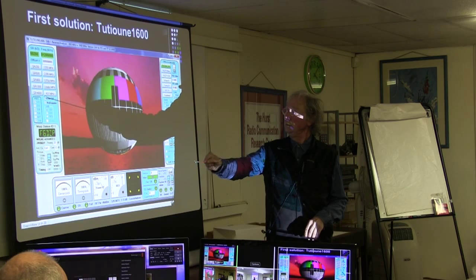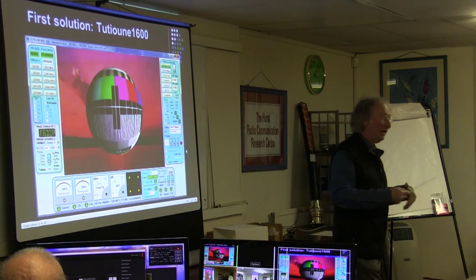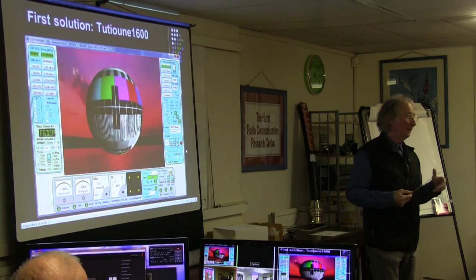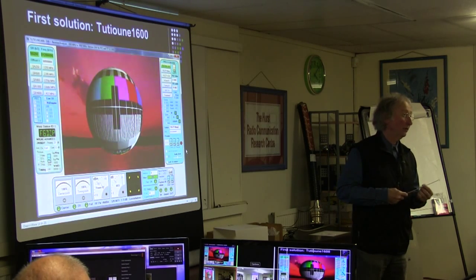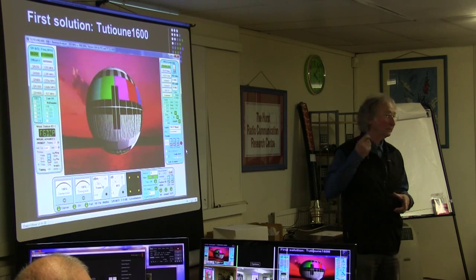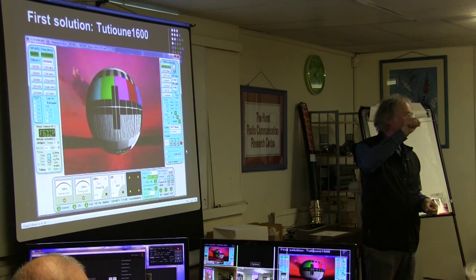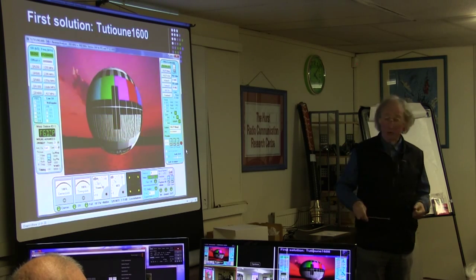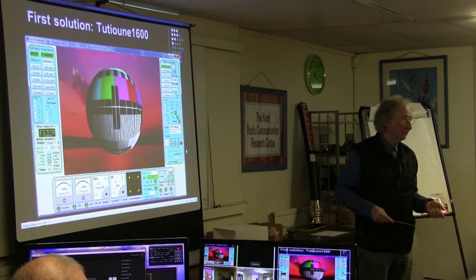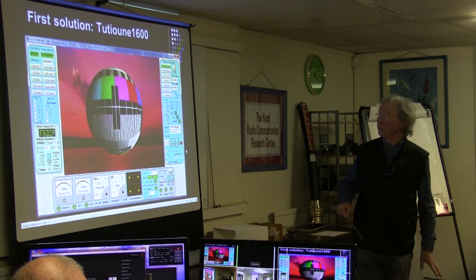When you ask for low symbol rate, that will change many things inside, not only the frequency of the master clock, I have said, not 120 megahertz, but 60 megahertz. But it will change many things for the work of the derotator.